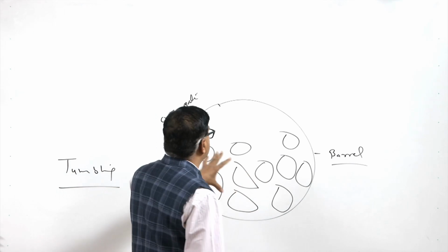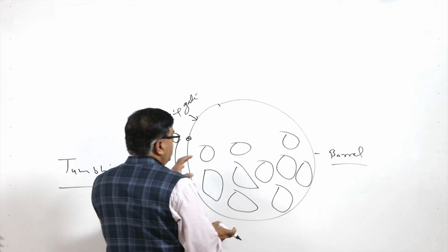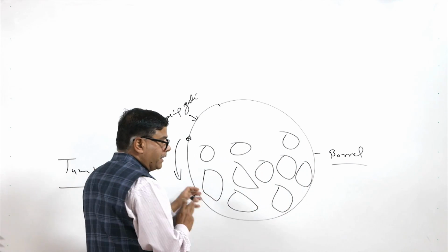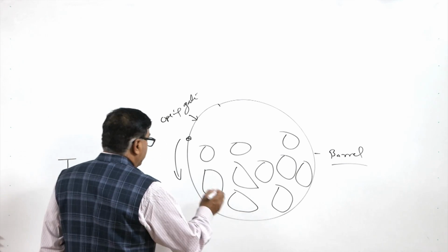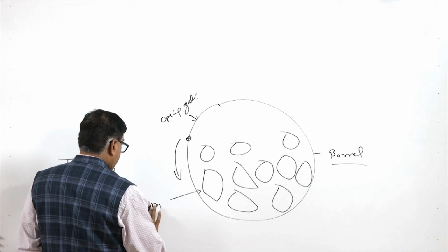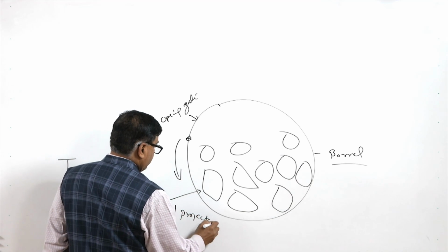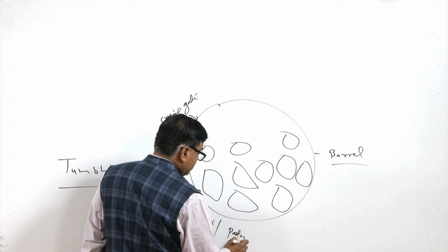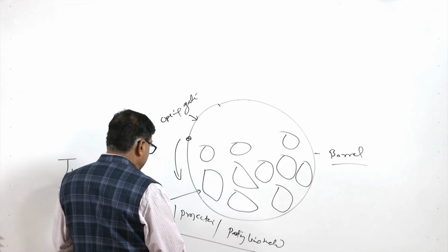so that when the barrel is rotated, the surfaces of the castings will come in contact with each other and they will be rubbing each other. So, in this process all the fins or the projections or the additionally deposited metal at the parting line, all those are easily cleaned.